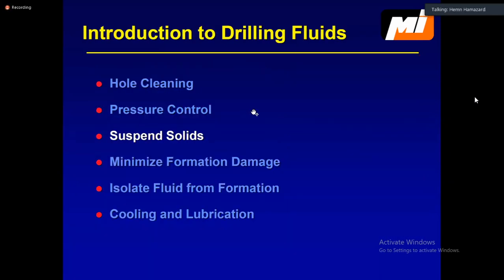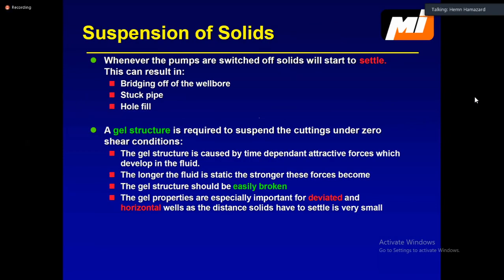Another function of the drilling fluid is suspending cuttings. When you are drilling any hole, there are many cases where you need to stop pumping. That means you are not pumping any mud into the hole, so the movement of the fluid in the annulus will be stopped. That means a static condition. In that static condition, the rheology of your mud, which is called in this case gel strength, should be sufficient to carry all the cuttings, which are halfway. You are trying to bring them back to surface, but they are still halfway or a quarter of the way. You stop for a connection or for any other reason.